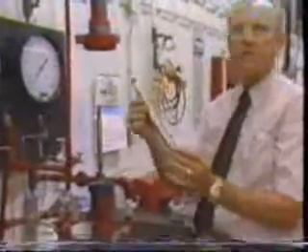So he makes that adjustment, he assembles the valve, and it looks like this in the assembled, ready-to-test condition. That valve is in the test block. Now, we will close the test block and run a test on this valve to determine its calibration pressure and then to make changes as required. This gauge will be the casing pressure. This gauge over here will be the tubing pressure.